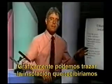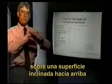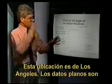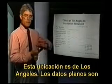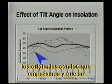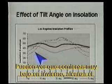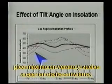Graphically, we can plot the insolation that we would receive on a tilted surface at different times of the year. Pick the location for Los Angeles, and we're looking at the effect of tilting the modules up from horizontal. The flat data is the actual original data that we started with that's measured at weather stations. And you can see that it begins very low in the winter and peaks in the summer and falls back down again in the autumn and winter.